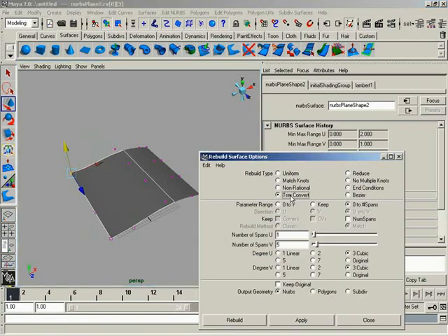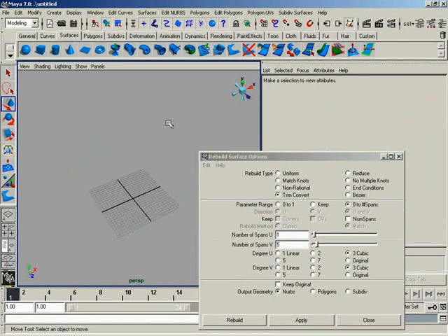Now down from here, we have trim convert. And what this is going to do is allow you to take a trimmed surface and make it no longer a trimmed surface. You actually make it into a real live NURBS surface that no longer has a trimmed edge. Now, before you get all excited and think, wow, if I've been using trims, because sometimes when you use trims, you'll have tessellation issues, or it might be difficult to create a surface that molds perfectly into a trim surface.